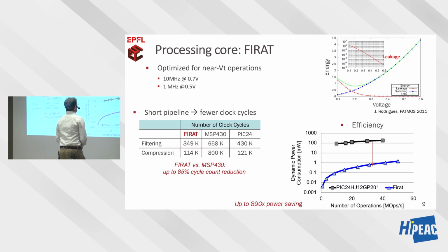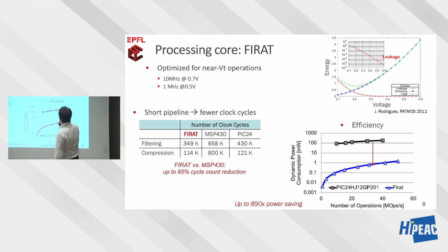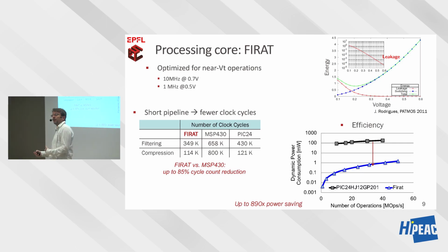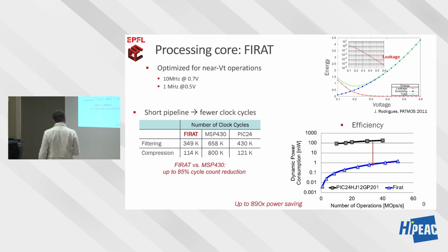Again, this is why we want to work at low voltages, because the dynamic power consumption decreases dramatically as we lower the voltage supply, up until a certain threshold where leakage starts to dominate. But this crossing point is usually pretty low, and at these levels you start to have a bunch of other problems related mainly to the reliability of SRAMs. Again, more on that later on in this lecture.